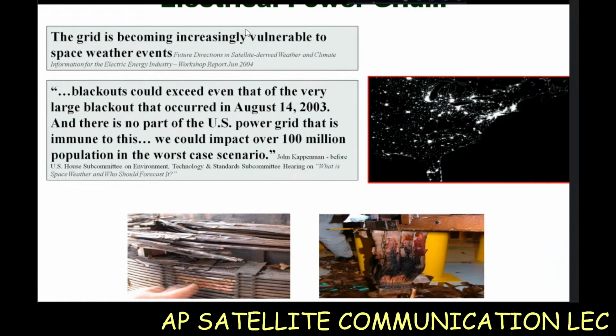In some cases, solar radiation is highly energetic and could cause power grids in some countries at high latitudes, not so much in the equatorial region, to trip. Suddenly these highly energetic particles emitted from the sun carry an electric field with them, and when they couple with the Earth's geomagnetic field, they could induce a huge amount of current in the power grids, like 1 million amperes. That is something the power grids are not designed to handle.